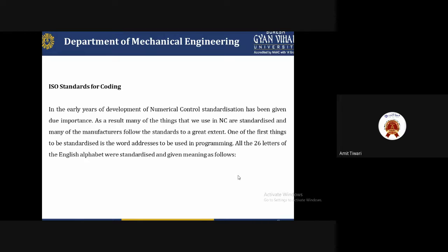Coding is simple, but you have to keep in mind that each and every code has a different uniqueness and will not be repeated again and again. So whenever you operate something for spindle speed, you have to use the S command. They are different types of operation as per the different alphabets, which represent that particular operation.